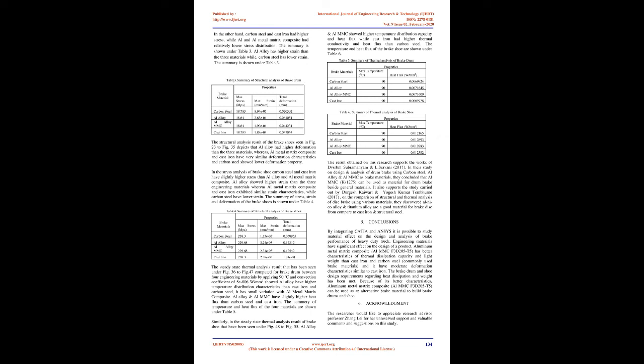Carbon steel brake shoe showed maximum and minimum temperature of 90 °C and 82.451 °C respectively. The maximum and minimum total heat flux of 0.012165 W/mm² and 0.00017827 W/mm² respectively. Whereas, cast iron brake shoe showed maximum and minimum temperature of 90 °C and 84.127 °C respectively.